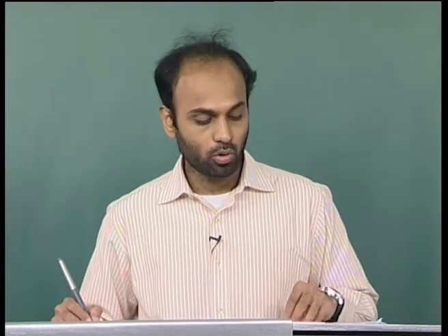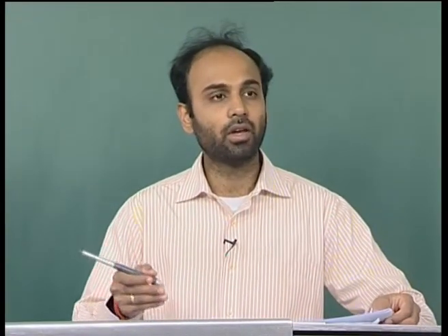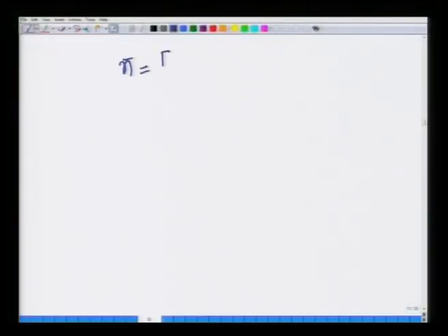Now, let me illustrate to you another technique to compute the power in the noise, because this is important, as we will do this manipulation several times. It is also useful to you in many other contexts. We said the noise vector n bar is nothing but the vector n1, n2, and so on up to nL. The noise vector n bar contains L components, that is the L noise components across all the receive antennas in this multiple receive antenna system.